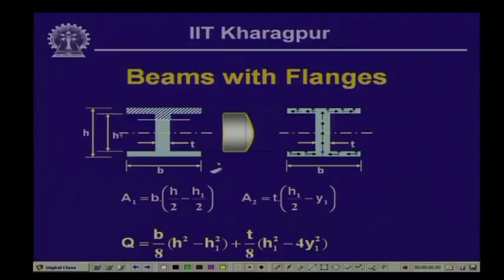Now, the question was how these two rectangular strips placed at a distance apart are going to be utilized as a cross section. Subsequently we looked into connecting these two rectangular sections by a vertical strip, and then we can use that section as a beam cross section, which turns out to be the most economical section for the transfer of bending stress. Now, if we use such sections for a beam subjected to load, and thereby to bending moment and shearing force, what is the consequence of shearing stress on such sections? This is the I section shown over here.